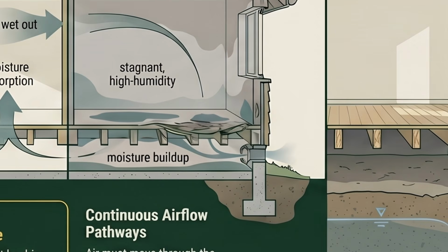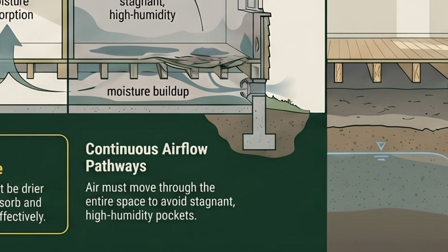Okay. So if it's the other way round, then that air coming in is actually just going to exacerbate the problem. So what you need is dry air coming in to then absorb the moisture, and then for that ventilation or airflow, and I think airflow is perhaps a better term here, because we want a flow of air, because we want that air to come in dry, to go through the space, absorb moisture, and then exit the space. So that's what we're actually doing. We're bringing dry air in, absorbing the moisture, taking it out and taking it outside.